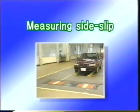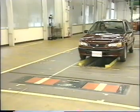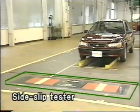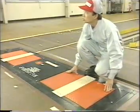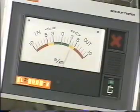One way to make an overall evaluation of wheel alignment is to measure the side slip amount of the left and right tires with the side slip tester. The side slip tester detects the sideways slip amount when the wheels cross over the laterally moving plates. Let's see how to do this.